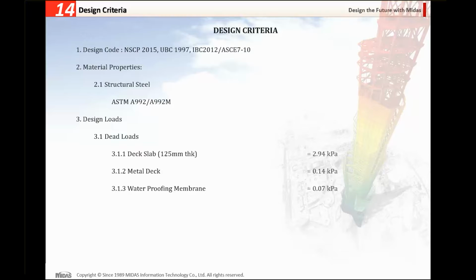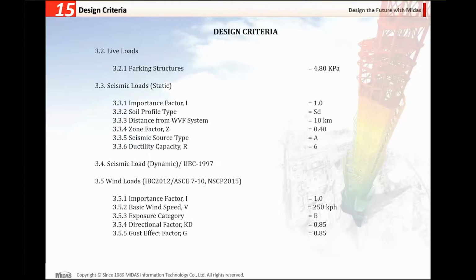The design load for the dead loads, we have the deck slab, which is 2.94 kPa, the metal deck, 0.14 kPa, the waterproofing membrane, 0.07, and for the live loads for parking structure, we will consider 4.8 kPa.